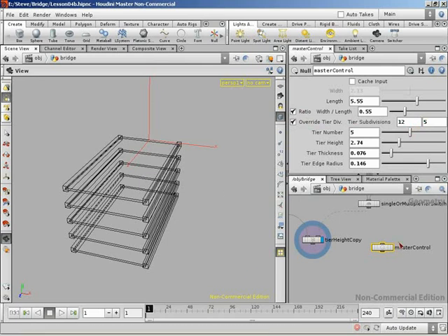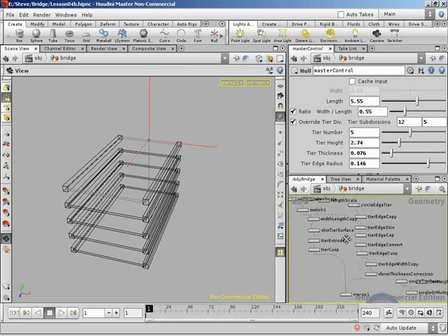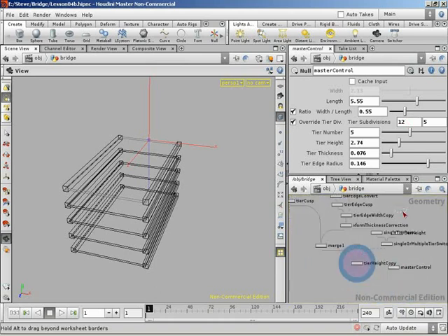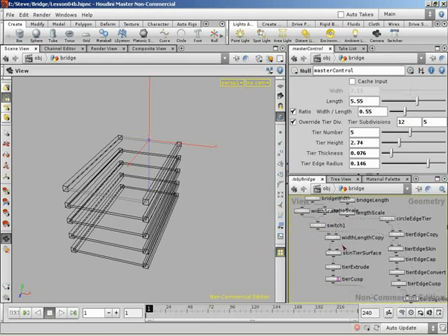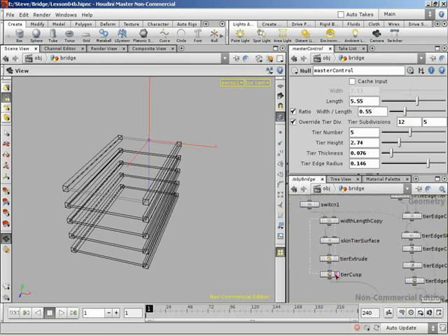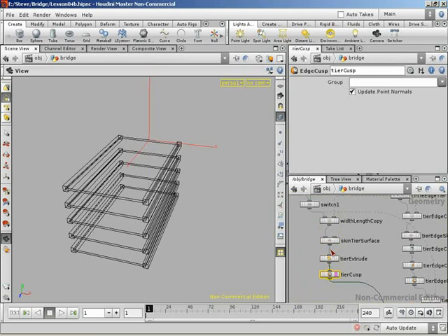So I just mentioned before briefly, this length is going to also control the number of crisscross patterns we're going to have, so it's worth keeping that in mind, and that's why this is being done in this video. Right. So if we come over to where we're copying, I'll grab this guy, bring him with us, where we're copying our length curve and our width curve to grab all these nodes.